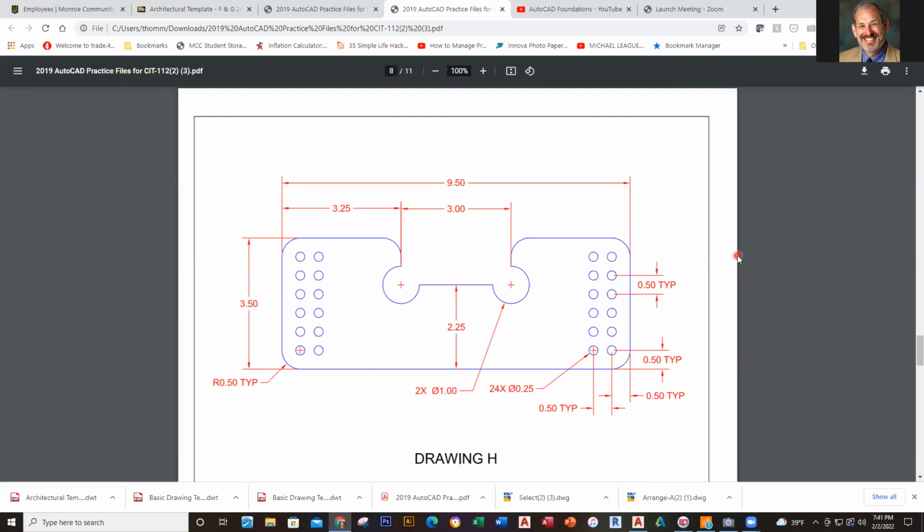Now, with this one, I'm going to use several different commands to draw this, okay? I want to give myself some basic geometry, and we already took a look at the trim command, so that's there. And then we're going to throw a couple other things in here. We're going to use offset. We just saw offset, and we're also going to use this a little bit further. Offset, and then we're going to make an array, which is essentially a pattern of copies. So let's just jump in.